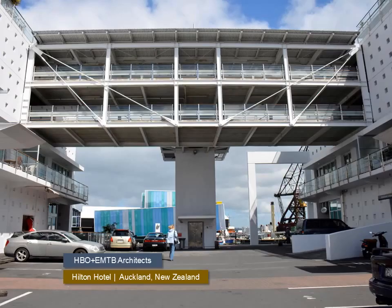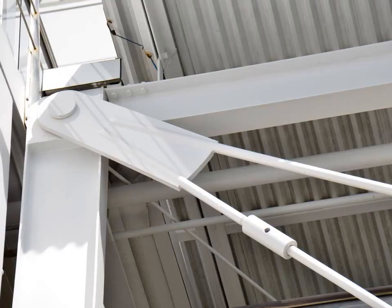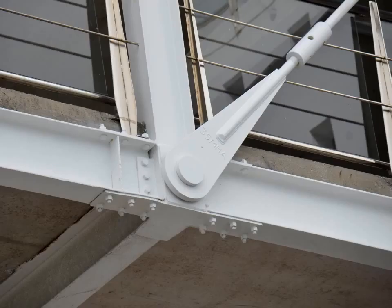A tension system is used here to assist in making the span, absorbing some of the gravity forces from the bridge-like connection between these buildings. The plates that connect the tension members to the primary structure are custom formed to accommodate two rods. A turnbuckle is evident. These are used to align and tighten the system as it is being erected. The connector at the lower extreme of the tension member keeps a similar aesthetic, but only needs to resolve a single member in this case.